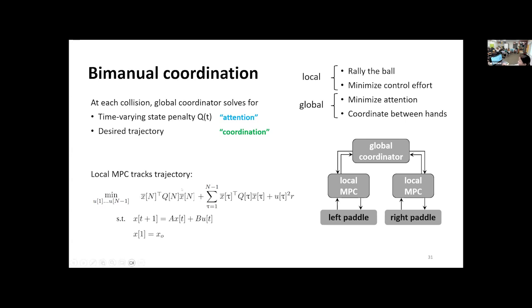So we have some terminal costs, but throughout the trajectory, at every time step, you care about this quadratic term of Q and x. If the Q is large there, that means I really want the x bar, the error, to be small. And if the Q is small, then I don't care. Then this last term here is just an energy or control effort penalty term.